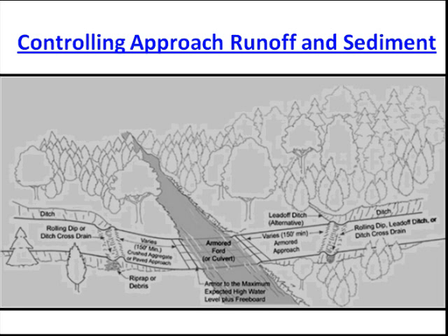Crossing a stream at right angles is the best approach and is a criterion of the stream crossing standard. However, aligning a crossing and its attached road at a right angle to the downstream axis of the channel also creates runoff pathways that can contribute large amounts of sediment to the stream system.